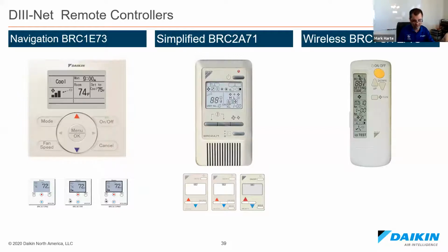I've been with Daikin 14 years. I think I've only replaced like 3 of them, and it's usually the red light that goes bad in it. But it shows set temperature, not room temperature. So if you do assisted living facilities, it's very good for that because they think it's 72 degrees in there. The wireless controller, I don't see a lot of that used with commercial jobs. And our ductless mini splits have their own wireless, so I don't see that used a lot.